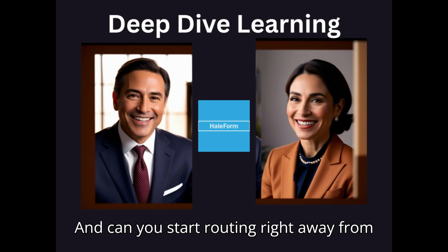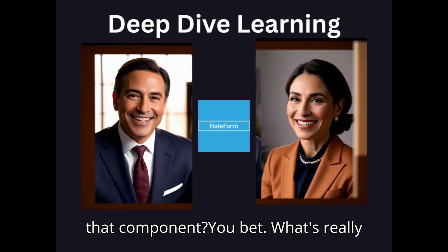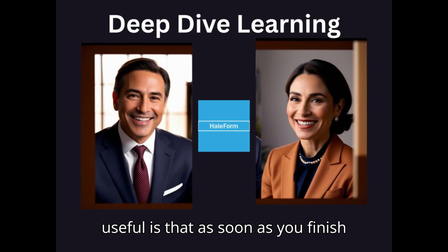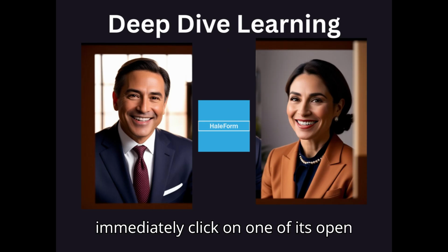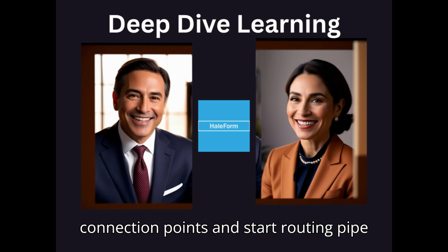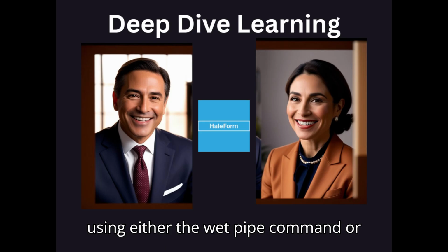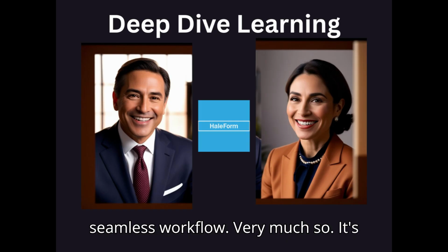And can you start routing right away from that component? You bet. What's really useful is that as soon as you finish placing a component like that, you can immediately click on one of its open connection points and start routing pipe using either the wet pipe command or maybe the quick route command. Nice, seamless workflow.